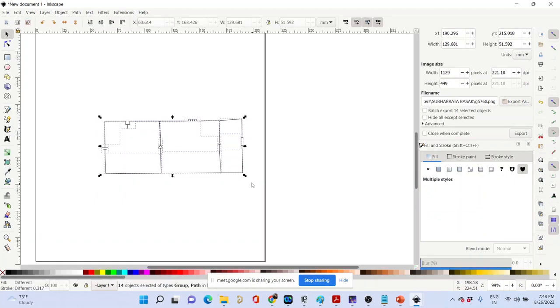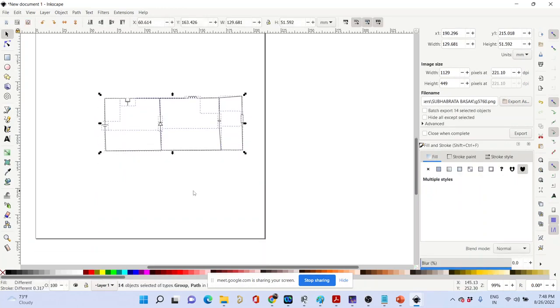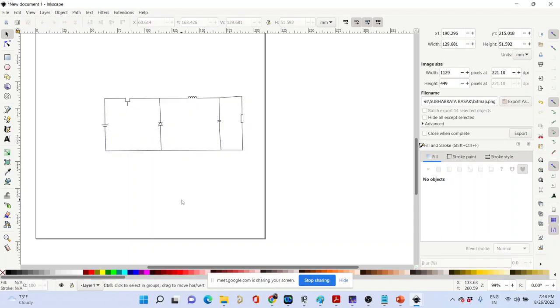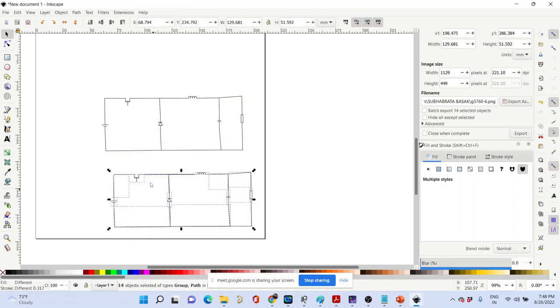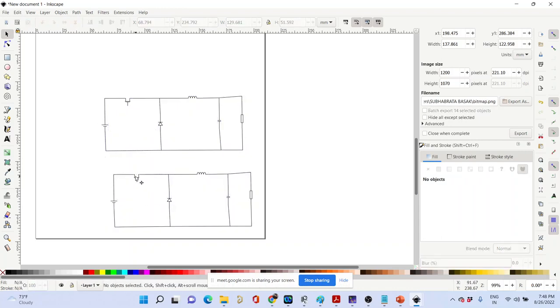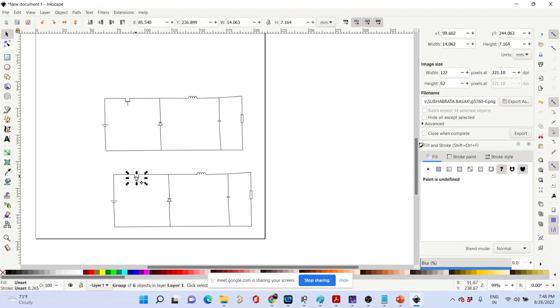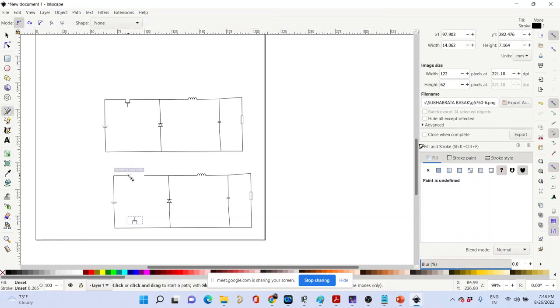Next I have to find IB value. Now I use IB equal to VB by ZB. Here, given that ZB equal to 20 at angle 60 degrees. So IB will be 100 at angle minus 150 by ZB equal to 20 at angle 60. Therefore, IB will be 5 at angle minus 60.